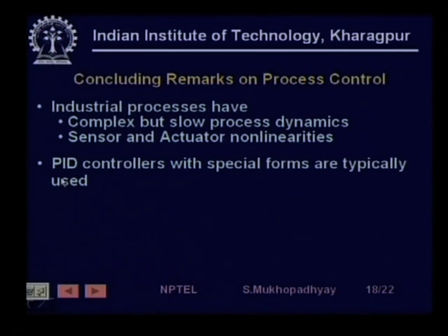And typically, I think, in around 90% of the cases PID controllers are used, sometimes with various special configurations for anti wind up, for bumpless transfer, etc., as we have seen, and special structures for feeding back derivatives, but generally the controllers are PID.